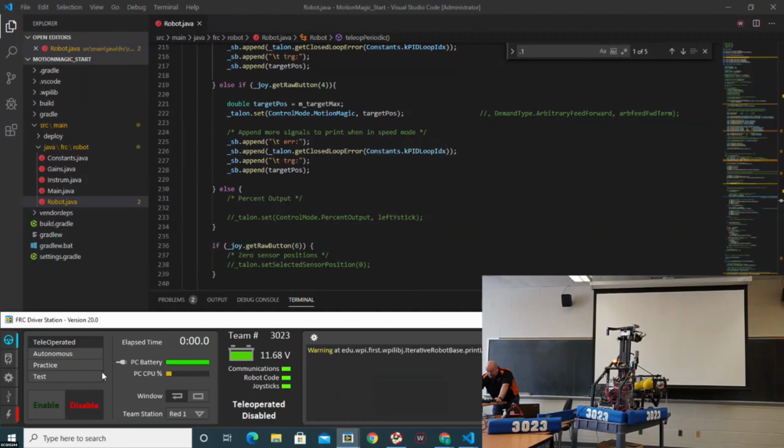Enable the robot. I'm gonna go to the max height. I'm gonna disable the robot. Somebody moved it, and you can imagine if this was an arm that was commanded to go down, somebody moved it up, and the robot was re-enabled, the arm's gonna come smashing down and potentially injure somebody. Enabling the robot made that move again. So what's a good idea to do?